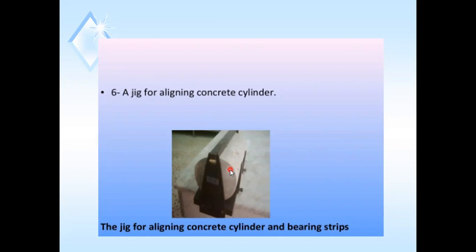Okay, we have taken almost 9 samples, like your concrete cubes. We have cast 9 cylinders for the same. The diameter of this cylinder is 150 mm and the height of that cylinder is 300 mm. In this fashion, we are going to keep this cylinder in our compression testing machine, and from the top, you are going to apply the load.